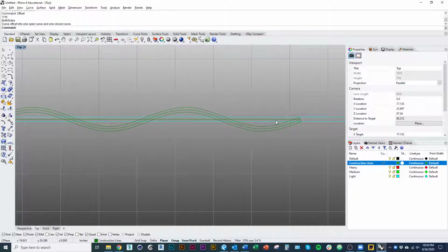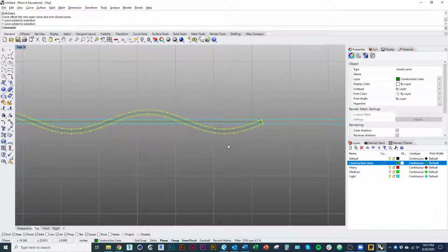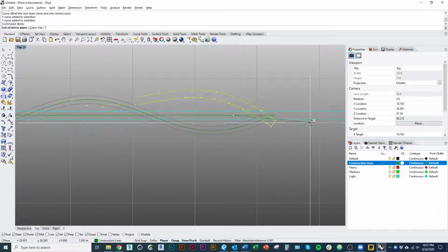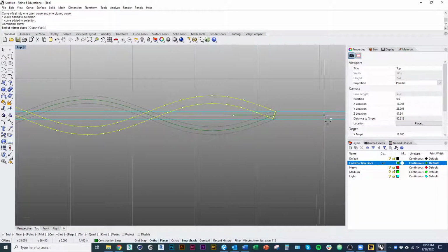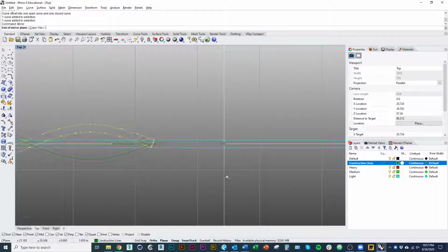The other thing I need to do now is, because we're actually twisting a 3-dimensional flat bar, it's not just waving in one dimension. We would actually see it from the other side as well. So what we would do then is take that offset line, use the mirror command, and mirror across our center axis. I'm holding Shift. You may find it hard to hold Shift sometimes and not snap to things.